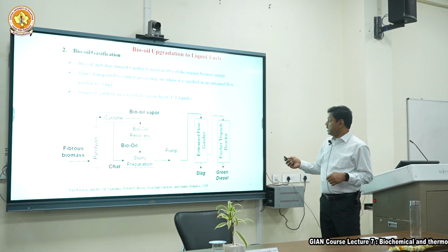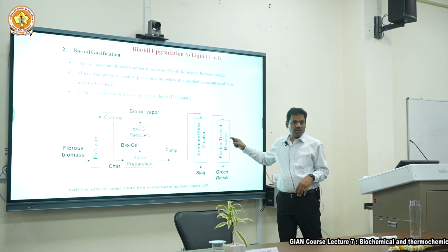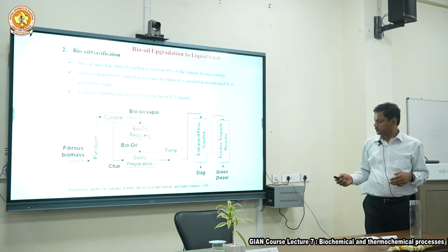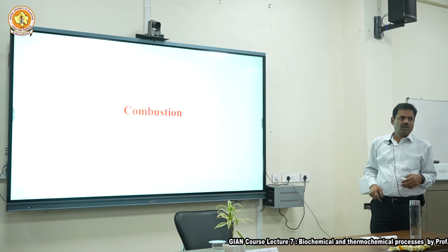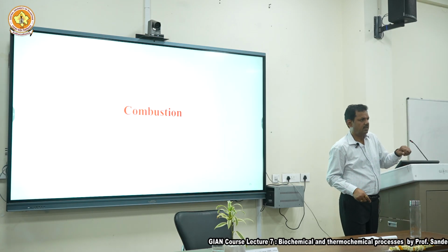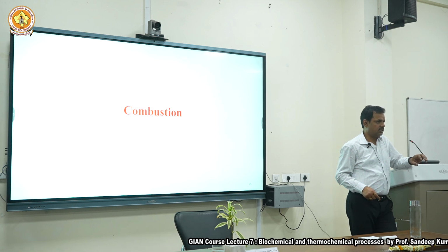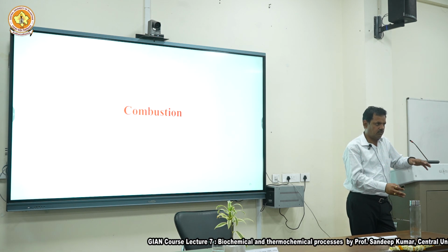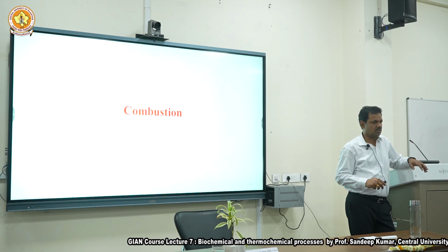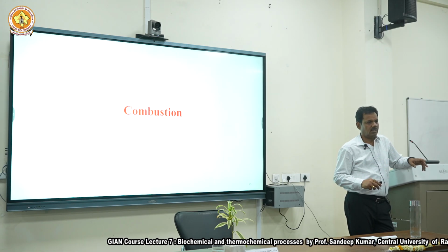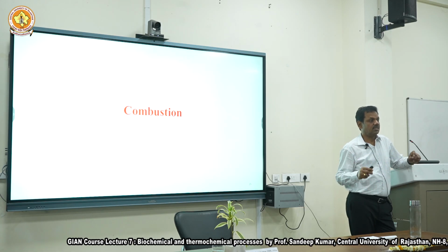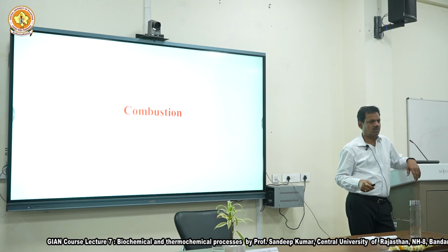You can gasify and then run a Fischer-Tropsch reaction, a catalytic reaction. You can do that. So that's why we make bio-oil liquid by pyrolysis. You have to make bio-oil first and then do hydrogenation. And through pyrolysis you can make diesel, and it has been shown. The challenge is cost, how efficiently can